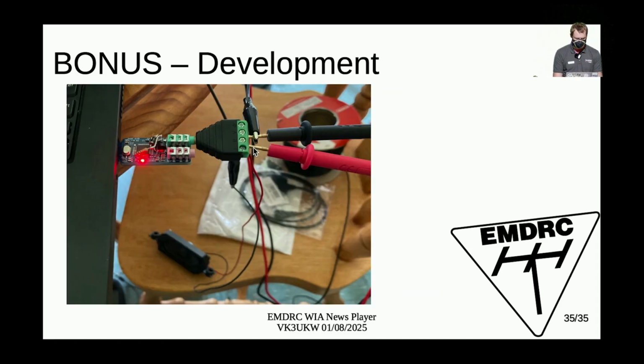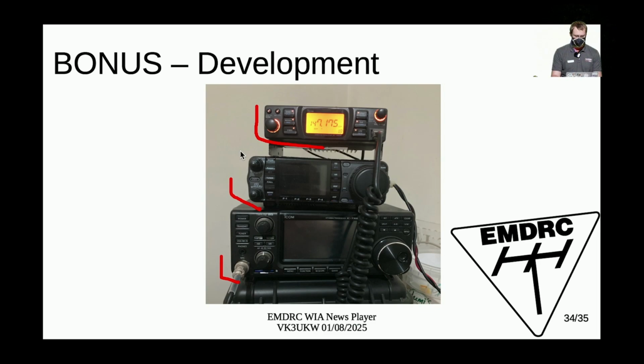There's one of the very first experiments where I've got a little speaker just plugged in there, and I'm just trying to see if I get anything coming out of it. Oh yeah, and the PTT control connection was connected to a multimeter in conductivity mode, so that whenever the PTT went down, it gave a nice loud annoying beep. And that told me that my PTT implementation was working. And that's it. All right.